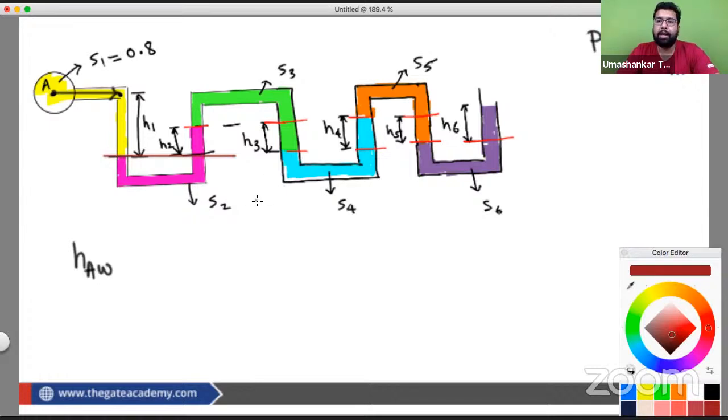Now again, let's start doing this question and compiling all this concept. So first of all, change everything to water. Let's suppose the pressure in this pipe is A, so this is HAW. Now moving in this horizontal direction, we need not write anything. We have reached this point. Okay, now we are moving downward.